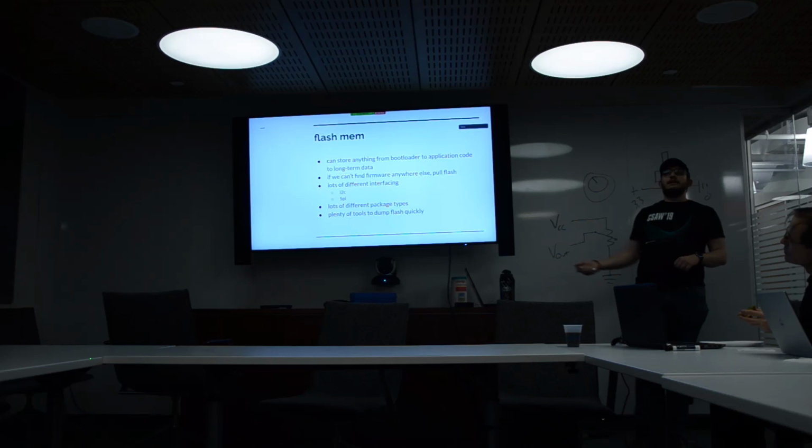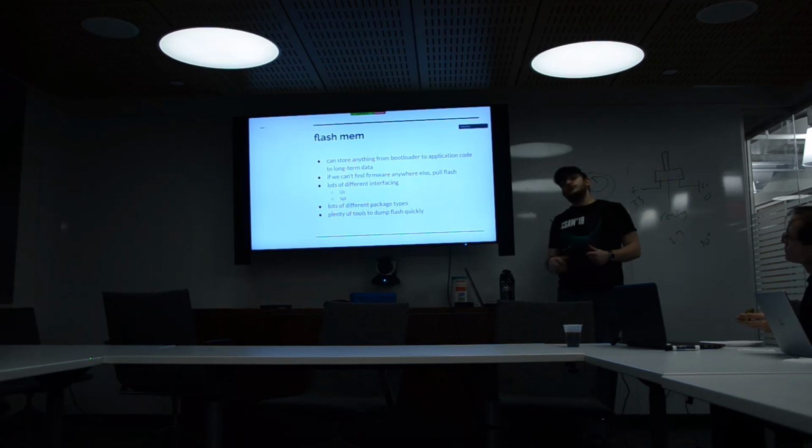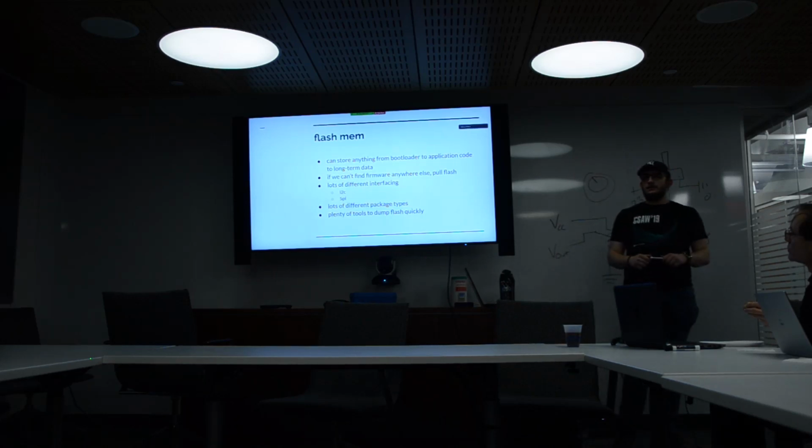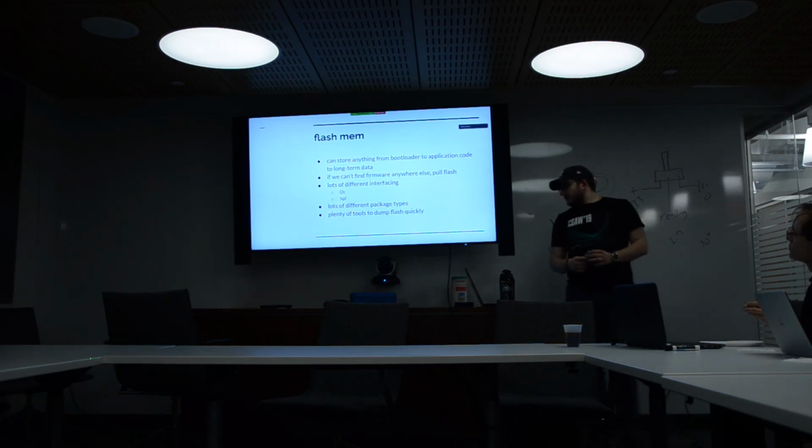If we're hacking an IoT device and we can't find the firmware online anywhere, one of the first things we're going to do is pull the flash off the board. That means different things on different boards and different types of devices, but you are literally removing the physical chip and reading it, because 9 times out of 10 they're not encrypted. Actually, I would wager that 99 times out of 100 they're not encrypted.